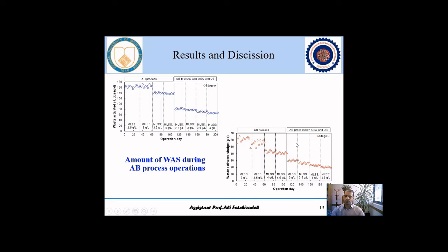Moreover, US treatment is an efficient way to enhance the release of sludge bacteria, which results in local high temperature, high pressure, and shock waves, enhancing the turbulence of the sludge medium and causing interparticle collision and the rupture of cell walls. After cell lysis, organic compounds re-enter the metabolism cycle of other microorganisms, and a portion of the carbon material is used for vital activities of microorganisms, which resulted in an overall reduction of sludge production.